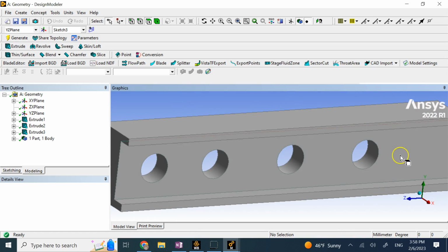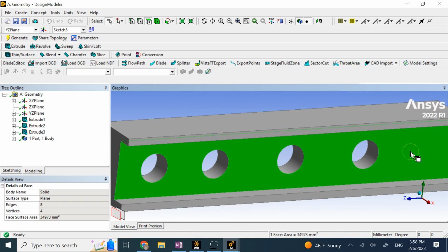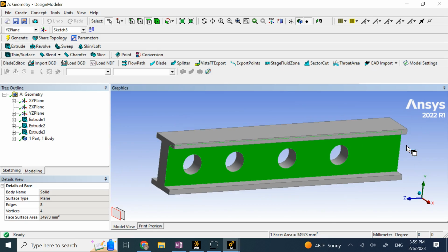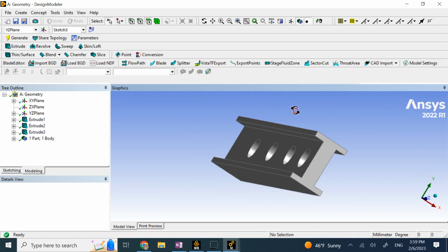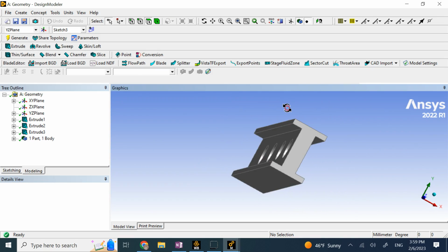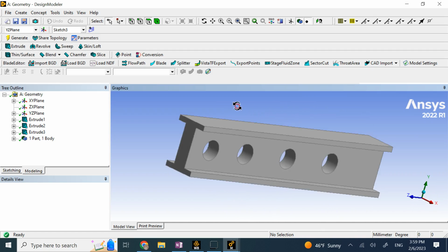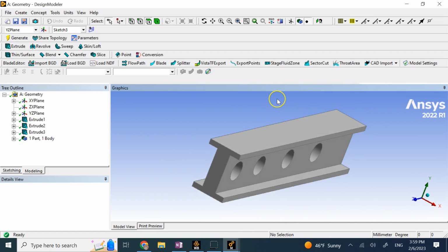Or let's say here on this surface, I have some small cut, or some small extrusion, which is, for example, the logo of the company. So I have some name here, extruded or cut extruded, especially extruded, and that is not going to affect anything. So instead of me having that small detail being a part of the finite element, I would remove that and try to only take to my meshing workbench and to my analysis workbench what matters in terms of the analysis. All those minutiae, just get rid of them.